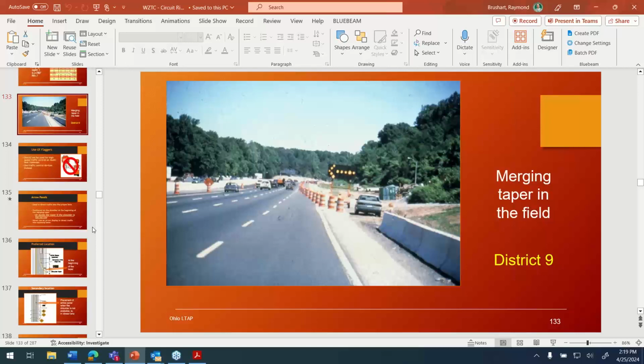And that's why in that typical application, in those situations, our crew's supposed to put a no passing regulatory sign on the back of their shadow vehicle. And they don't use the arrow panel on caution mode in those situations either. That would be a conflicting message.